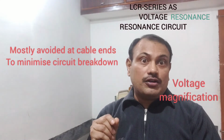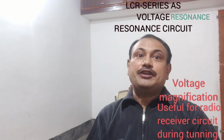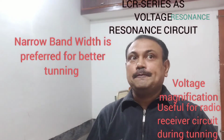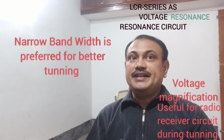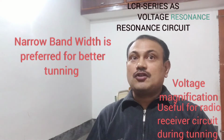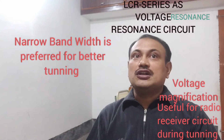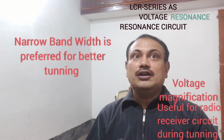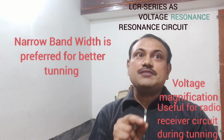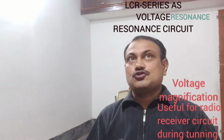However, this property is not always useful, so it is avoided, but it is useful in tuning. For example, it is useful for a radio receiver circuit during tuning, of course within the safe limit of VL and VC, that means the inductive and capacitive drops within that safe limit, to get an AC voltage of greater magnitude than the source voltage. When we tune receivers, the objective is to get an AC voltage of greater magnitude than the source voltage. At that tuning time, it is also useful.